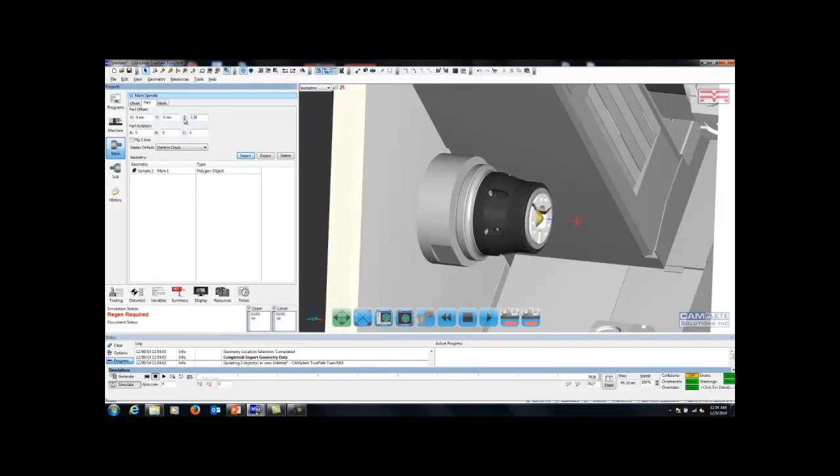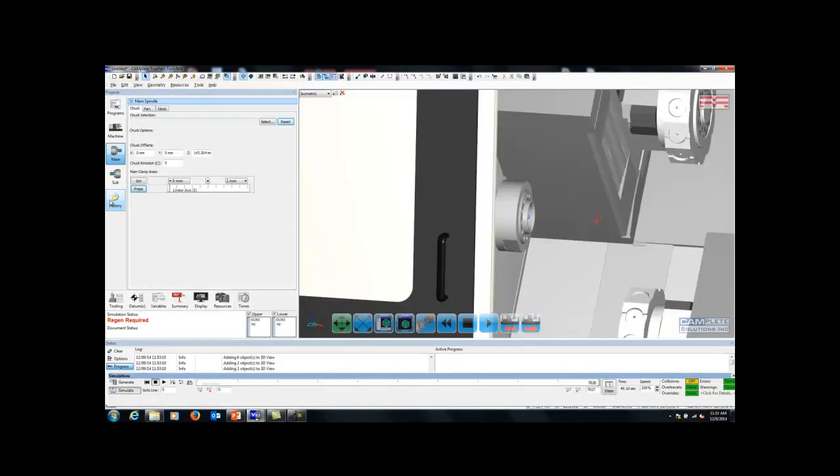Anytime you have tool paths, if you move your part in the work holding, all your tool paths will move with it because everything is associative. It's so simple. If I have a tool that's hitting the sheet metal, I can very quickly change that, regenerate, and move it so that everything is good, and instantly I've got updated code and updated tool lengths.